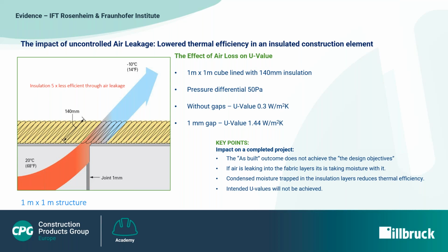Instead, its calculations are based on a theoretical thermal and vapour resistance of individual layered components in one direction only, either horizontally or vertically. The calculations do take into account spaces such as air gaps that make up the cavity or surface voids, but not the throughput of warm, moist air and the effect of liquid water ingress from either side. Consequently, the difference in the as-built outcome may not mirror the design intent. This is known as the design gap.